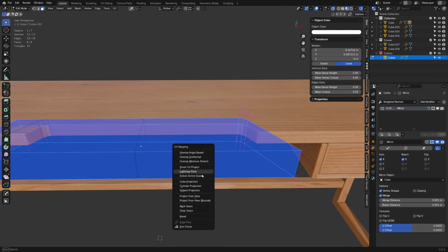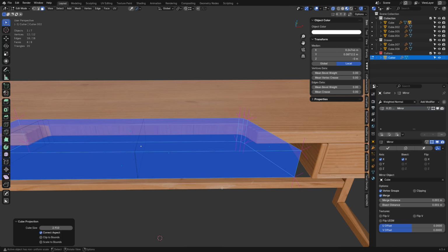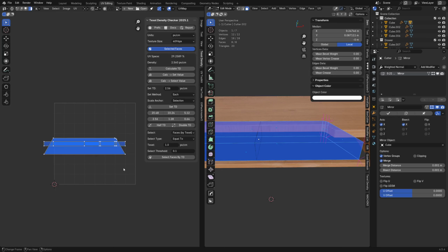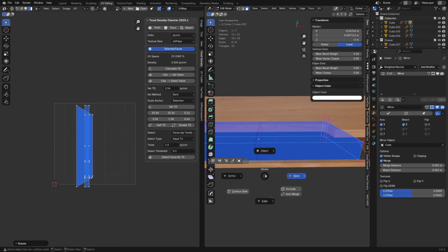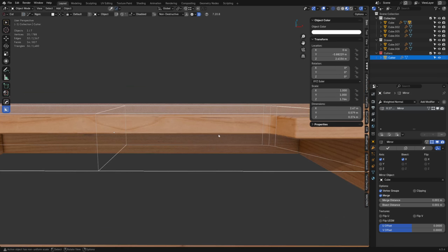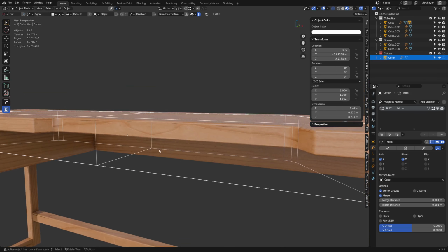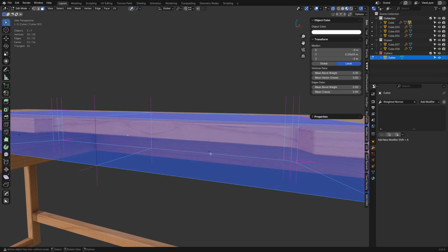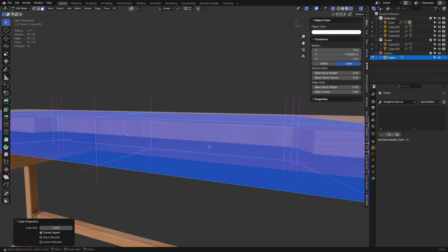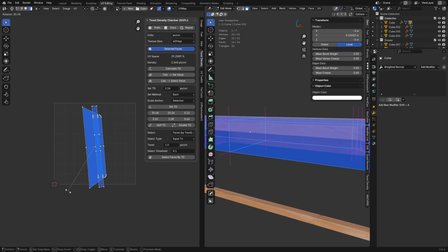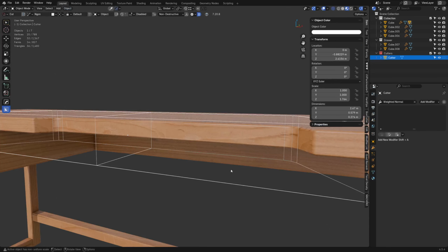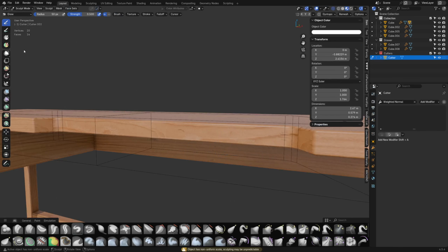So if we press U, and I'm just going to do a cube project for now. Or UV editor, it's sideways. Now we can actually unwrap it, and because of the mirror, you can see the bevel, the mirror, the butterfly effect there. So if I apply that mirror and then I cube project it, respin it every time, because Blender should unwrap left to right by default, but I don't know. It doesn't seem to really do that or know how to do that apparently.